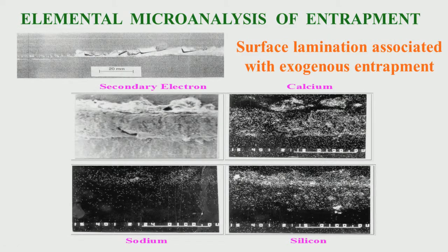So, from this metallographic analysis, and if you have the knowledge of continuous casting, steel making, steel refining, you know whether it is entrapment or whether it is a crack, you know which type of grade you are casting, you know what the type of solidification is. So, you can tell what the possible defects are, at what stage they have originated, and accordingly, if the defect takes place in future, you can take some remedial measures.